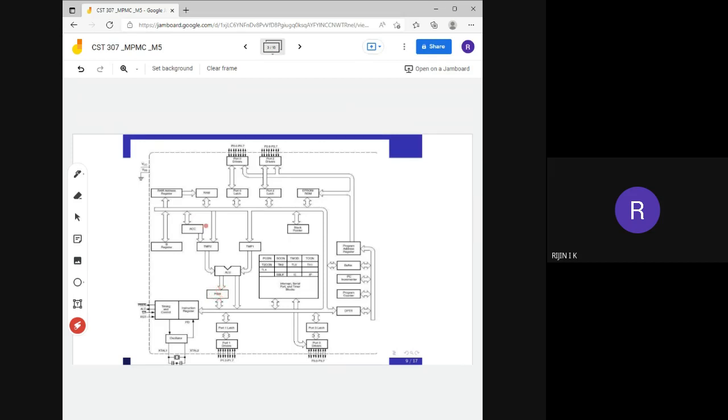Then the accumulator register is one of the operands while performing any instruction. One of the operands will be in the accumulator register, or sometimes the result will be stored in the accumulator after performing the operation. Then the B register is generally used in multiplication and division operations. Then the stack pointer is there. It is used to point to the top element in the stack.